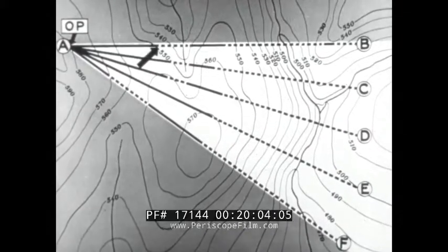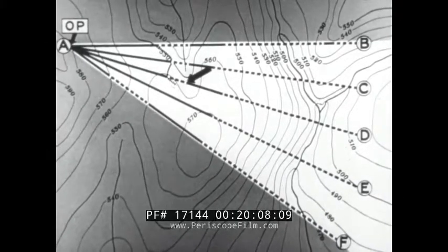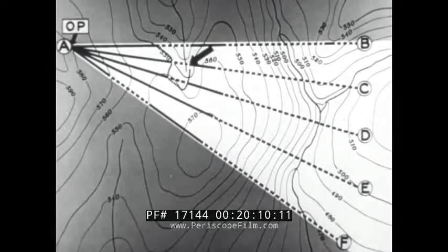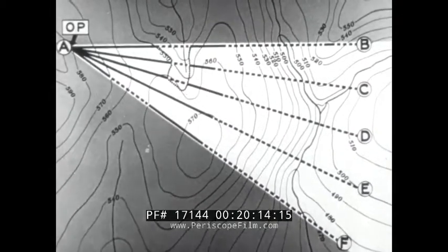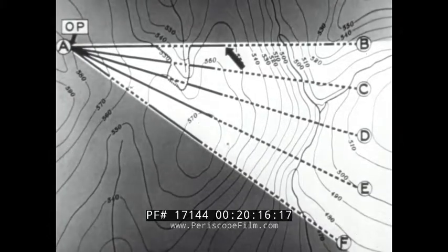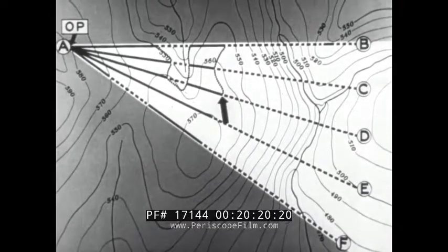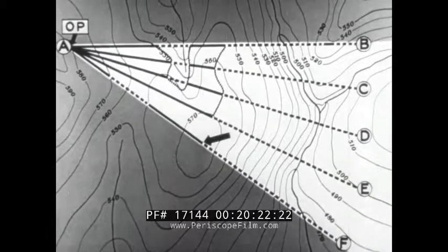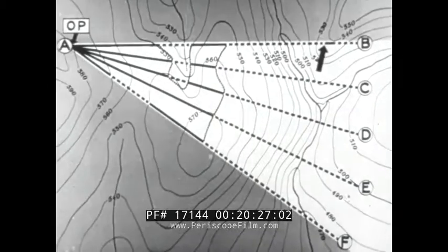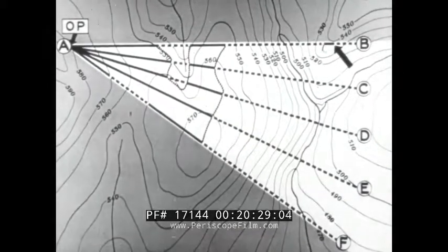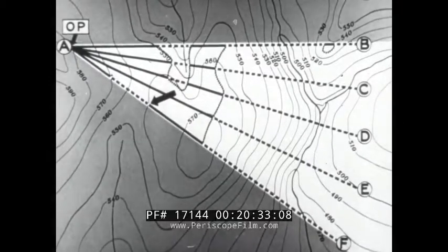Now outline the visible and invisible areas of the sector by a curved line, connecting the adjacent extremities of the visible and invisible portions of the lines drawn from A. The slope above the line just drawn is visible from A as high as the crest of this ridge, which hides nearly all of the sector which lies behind it. A small portion of high ground near B is visible. This small area is hidden from the observer.